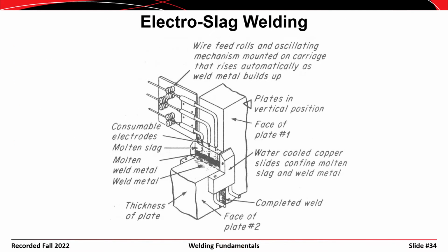Now, I won't speak too much about these processes except for electro-slag welding. Electro-slag welding has some applications in structural engineering, probably more for bridge engineering than buildings, but if you're going to fabricate large girders or join large plates together, then electro-slag welding has some benefits to it. Basically, what you do is you take your two plates together in the form of a butt joint, and you put a dam, and that's illustrated here. This is the water-cooled